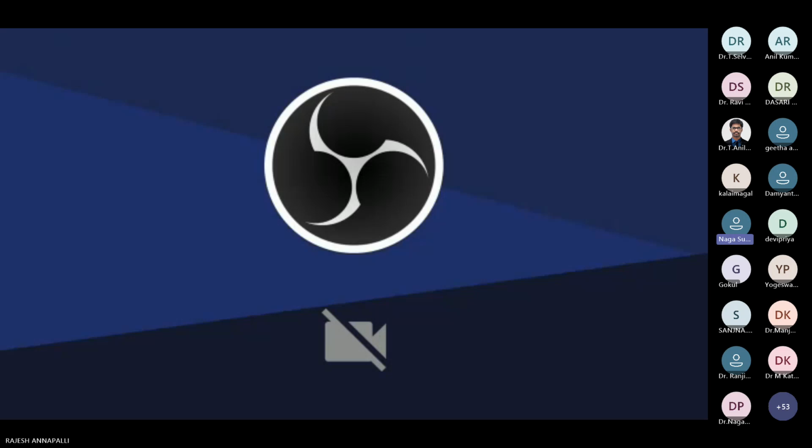We have only 40 port level signals, so you need to give the data through some of those, let's say 25 are inputs. You need to produce the data and give it to the 25 ports, and that will produce some output. You have to take the remaining 15 pins' outputs and verify it is producing properly or not. You will see the physical pins after